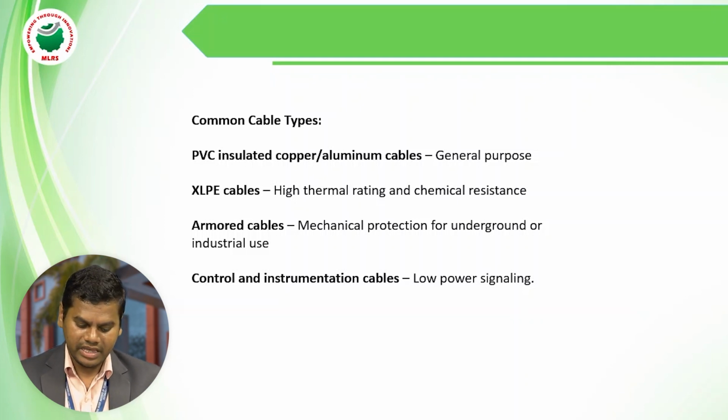Next, XLPE cables. XLPE is simply polythene cables. The polythene cables have high thermal rating and chemical resistance. Next, armored cable. Armored cable is mechanical protection for underground or industrial use purpose. And the last one, control and instrumentation cables, which are for low power signaling.